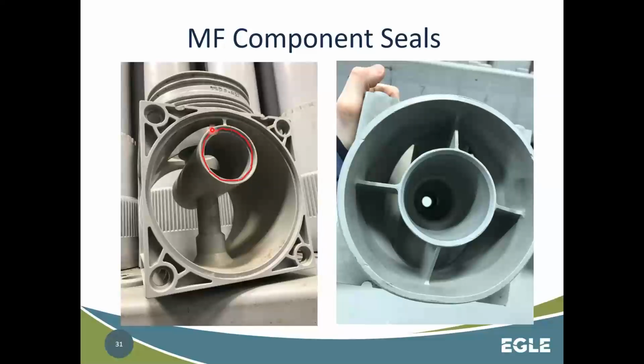So during installation, if that wasn't done correctly, your raw water could get pushed right into your finished water. So the installation of these is very important, and the initial testing is very important to catch any of those types of failures.